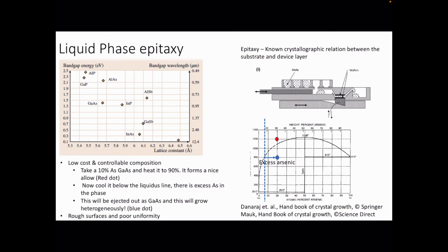One material to be noted is the GaAs and the aluminum arsenide layer, and anything in between is obtained by replacing a gallium atom in GaAs by an aluminum. So in these layers you get what is called AlGaAs layers. If you replace a gallium atom by an aluminum atom, you'll get an AlGaAs layer, right?